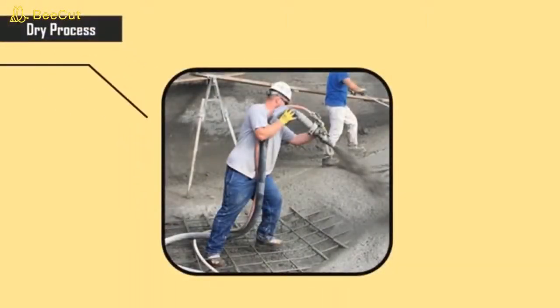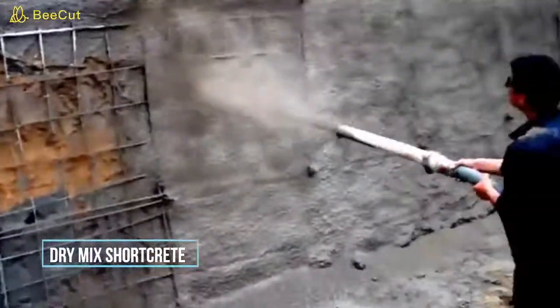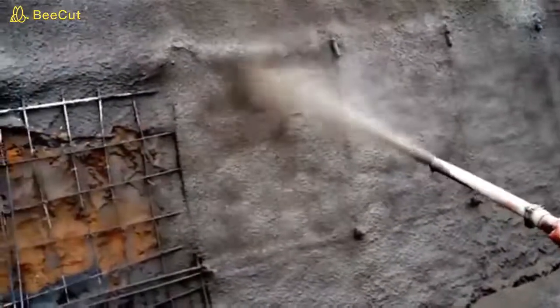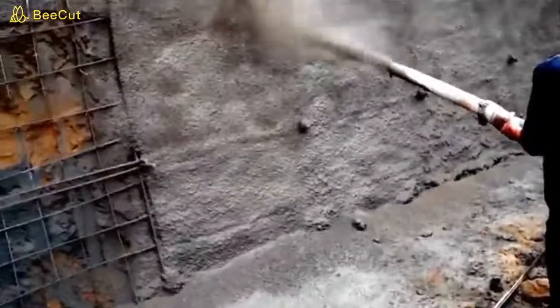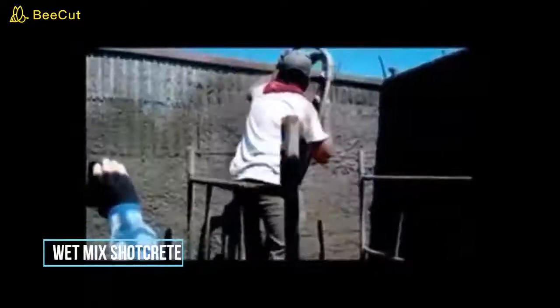Shotcrete can be in either dry mix or wet mix version. Dry mix shotcrete is a method of placing the dry concrete ingredients into a hopper and conveying them through a hose to the nozzle. The water is added at the nozzle during the spraying process. The concrete will be sprayed to the targeted area and will completely mix at the receiving surface. The process of spraying dry mix shotcrete may cause some dust from the dry mix ingredients throughout the entire spraying process. Meanwhile, wet mix shotcrete